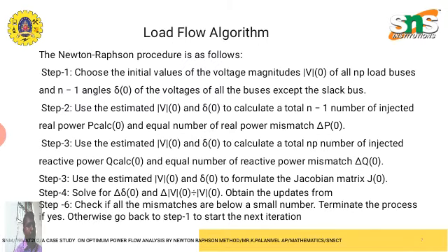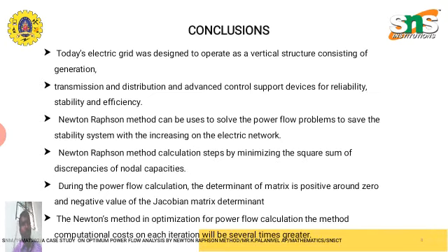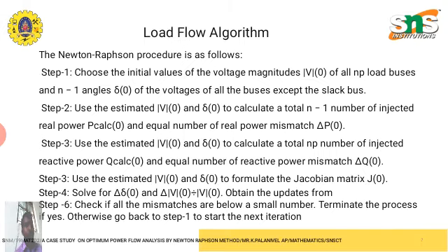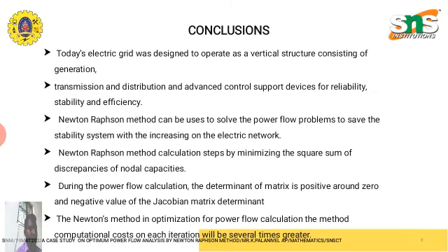For the formation of the submatrices, the Jacobian matrix can be simulated by using the active and reactive power equations. The Newton-Raphson load flow program is tested on the system, and data and initial conditions are given.